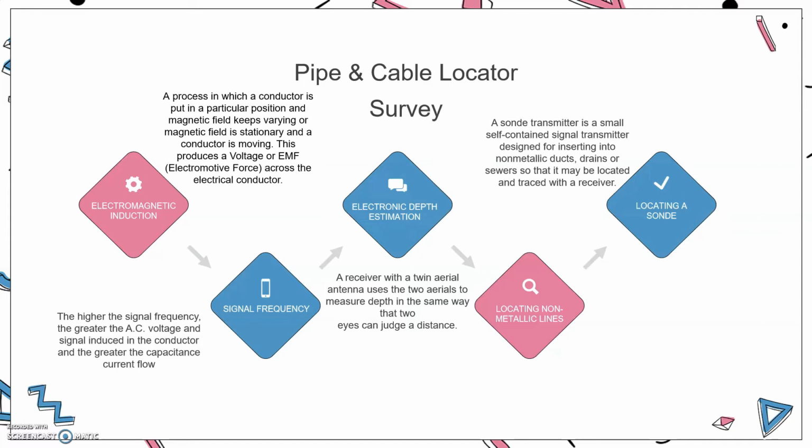A large pipe or cable diameter increases the surface area of the line which is in contact with the ground, so the signal leaks to ground. The same signal strength leaks away over a much shorter distance from a large pipe than a small one.